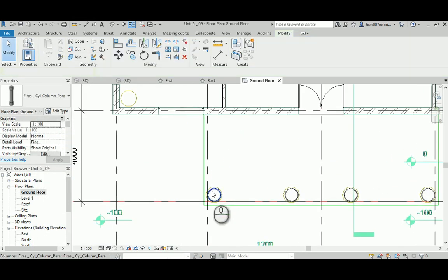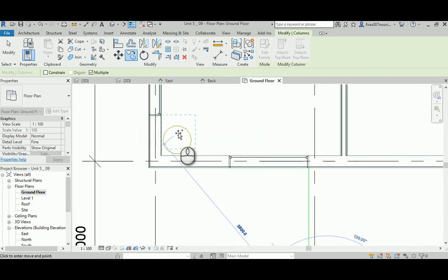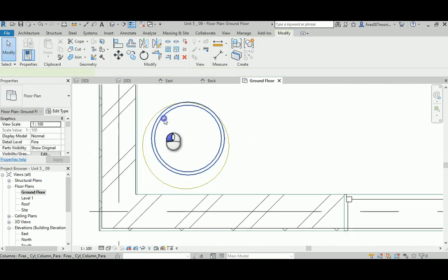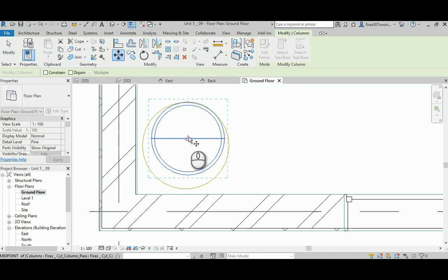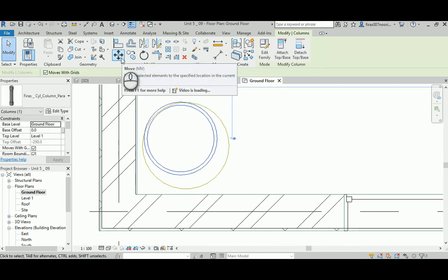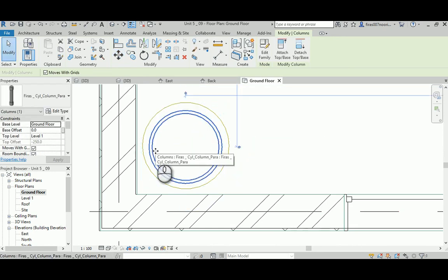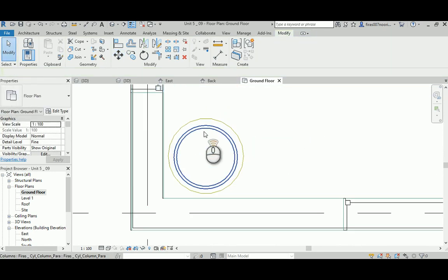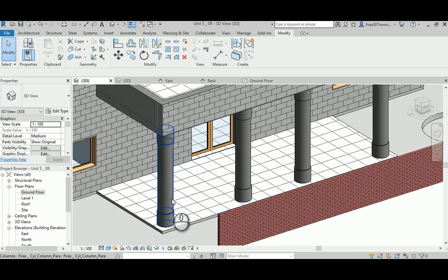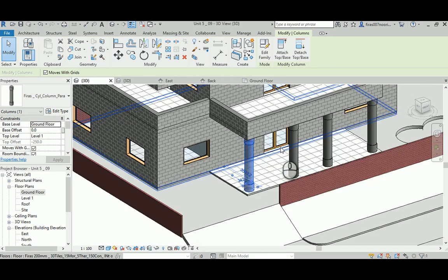Now I'm gonna select this guy and again copy. That's why it's called the type parameter, because it's gonna match itself to all the copies of that architectural element. It's the same column, the same width for all. So again, it isn't in the middle, I know. So type means that when you change this guy, it's going to change all the copies of this column.